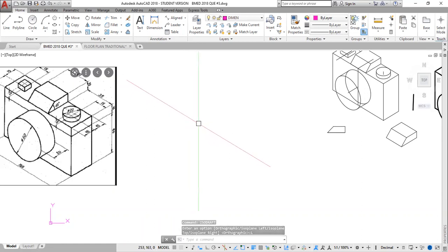We have the left face. Hold down Control and press F5 to change between faces. You will realize that those two lines are running flat, or horizontally. Press F5 again, and we change to the right face. It's important to note that the lines are restricted to angles of 30 degrees, and you're only allowed to draw on the selected face. If you try to draw on any other face, you will experience great difficulty, or in some cases, it's impossible.